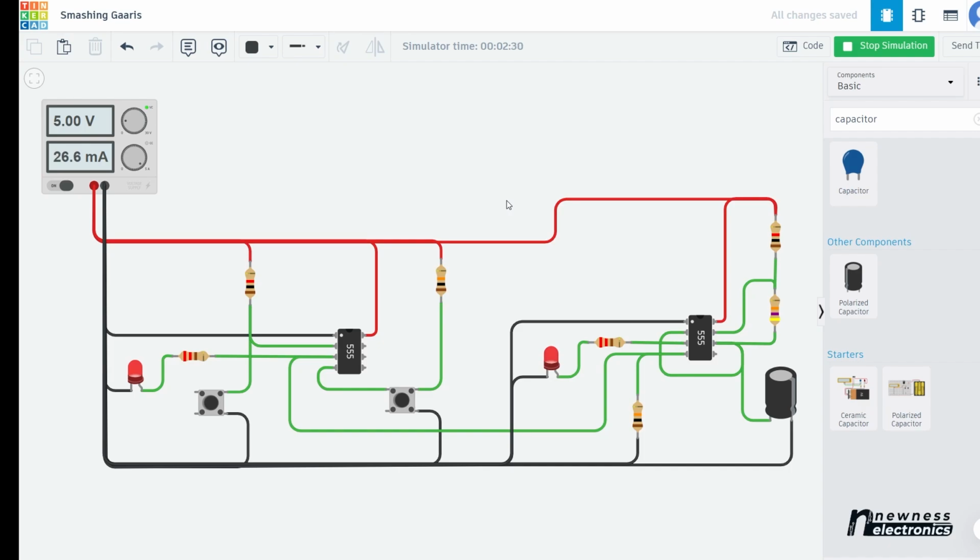I remember sometimes I built a battery charging solution with the 555 IC. So what I did was that when the battery is low, it will trigger this one. So this one was not a button. It was like a sensor, a part that measures the battery voltage. And when it is low, it triggers this one. And when the battery is full, another sensor measuring the battery voltage triggers the reset. So your battery doesn't overcharge. When it is low, it starts charging. When it is full, it stops charging. You see that? So depending on the imagination of your mind, that's the limit of what you can do with these ICs.